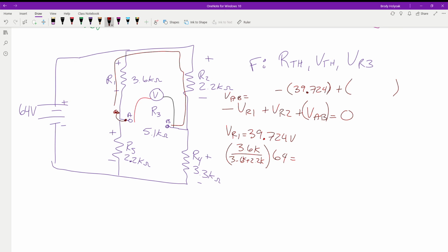So now let's find the voltage drop across R2. Okay, and how did you get that? Okay. That's using your clues that you have in your circuit. It saves you from having to do a lot of excess calculations. These two happen to be equal. So the 64 volts, you're going to get dropped across here. Well, what about this guy? Is that going to give you the same one, though?